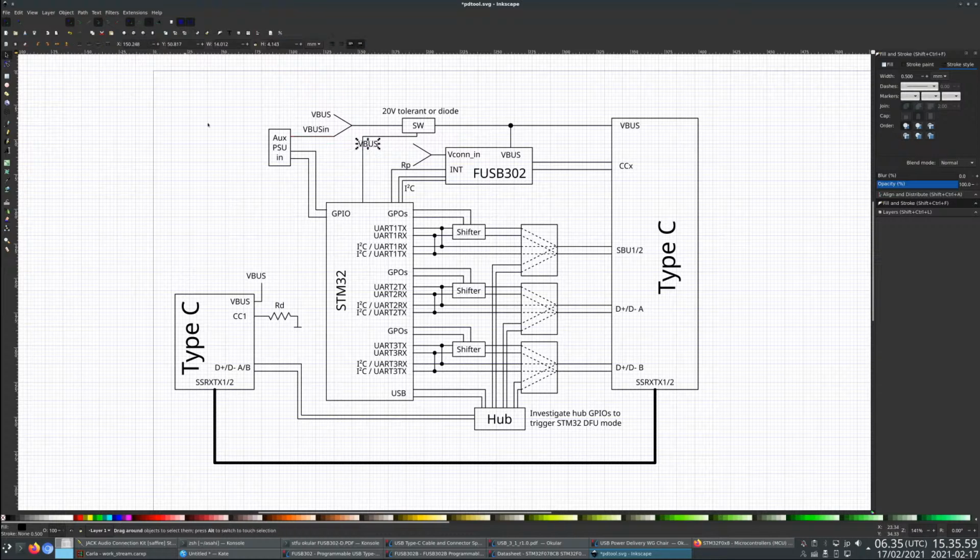Yeah, I mean, what I mean is that if we just define the local bus as not necessarily 5 volts, then we can get away without requiring a jumper, and it's safer anyway, because then we just design it with the assumption that it's not necessarily 5 volts. And in that case, that just means there's a little LDO here. And that is safer because this is a VCon option. So if we decouple that from VBus, it's safer anyway.